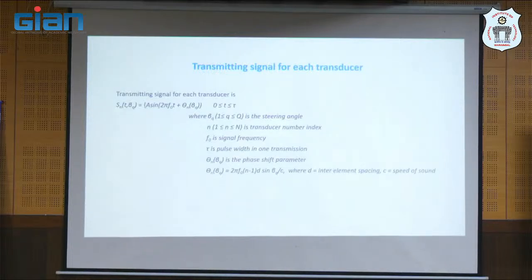Here, the phase shifter will give different phase shifts to each element. That depends on the number of elements, the inter-element spacing, and what frequency we need.